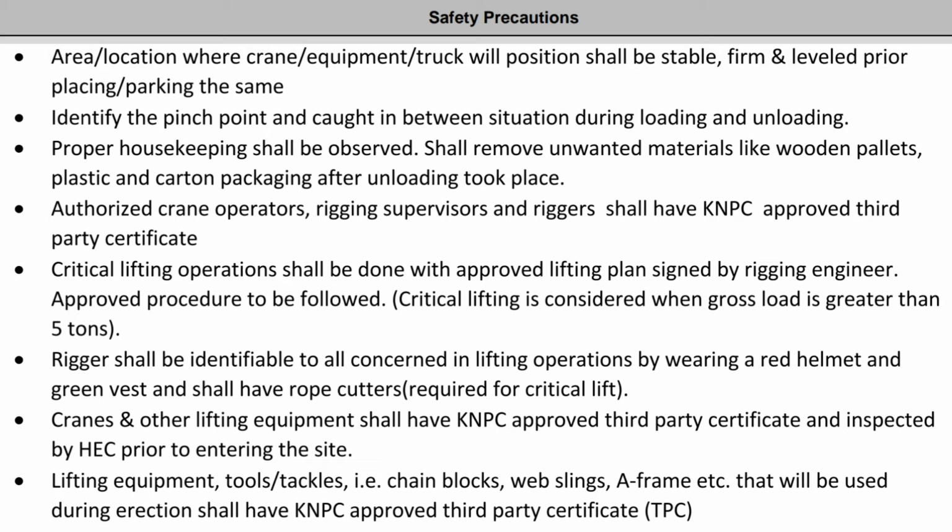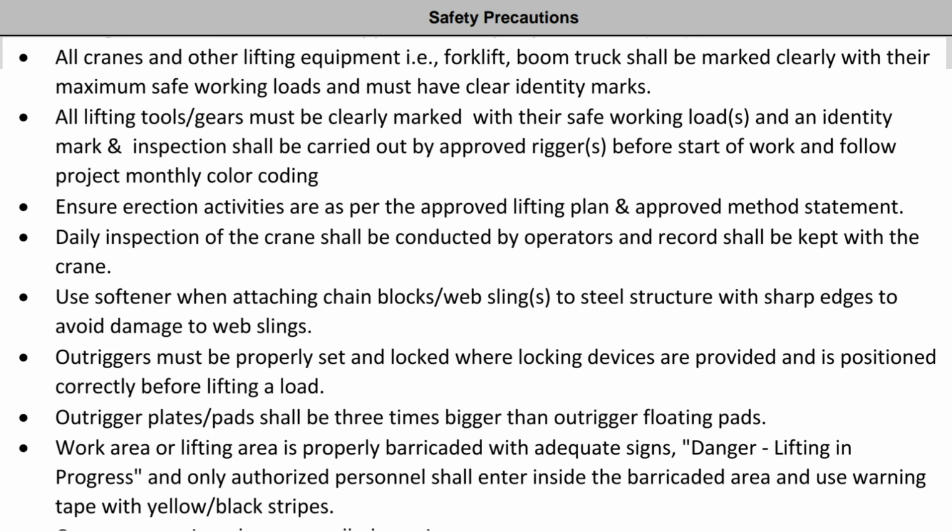Cranes and other lifting equipment shall have KNPC-approved third-party certificate and be inspected by HEC prior to entering the site. Lifting equipment, tools, tackles, that is chain blocks, web slings, A-frame etc. that will be used during erection shall have KNPC-approved third-party certificate, TPC. All cranes and other lifting equipment, that is forklift, boom truck, shall be marked clearly with their maximum safe working loads and must have clear identity marks. All lifting tools and gears must be clearly marked with their safe working loads and an identity mark.